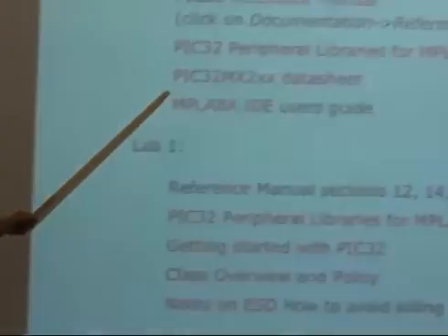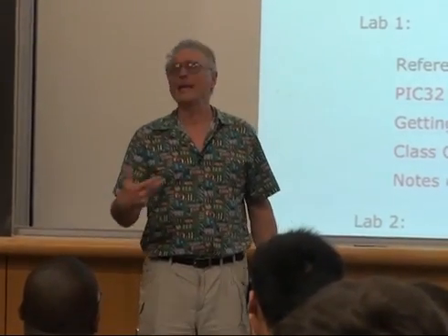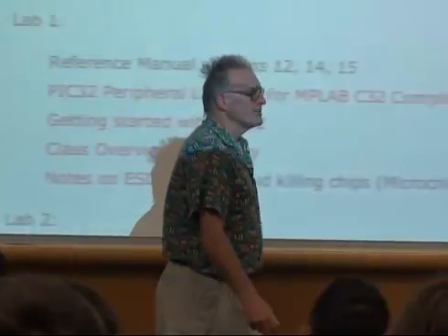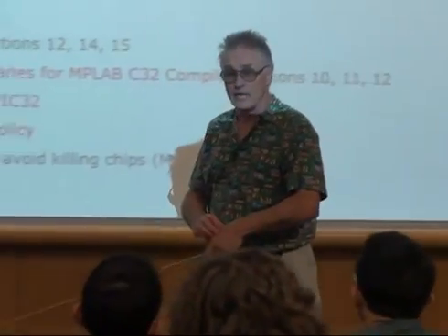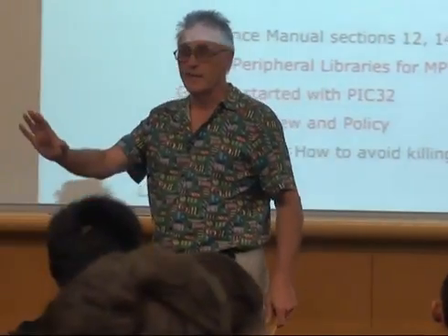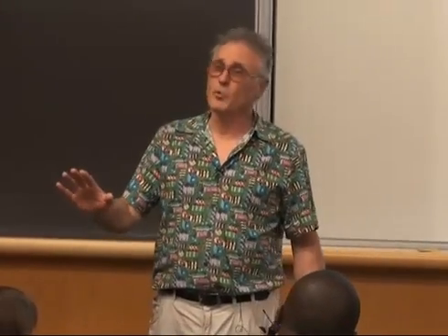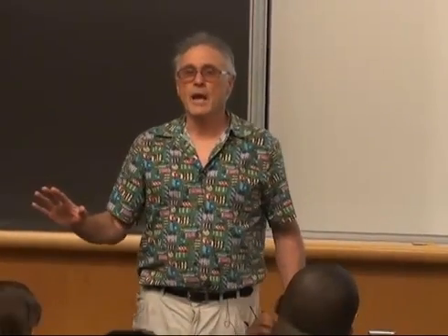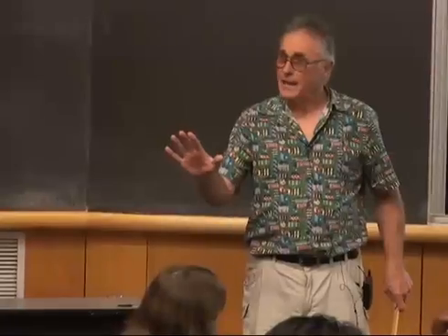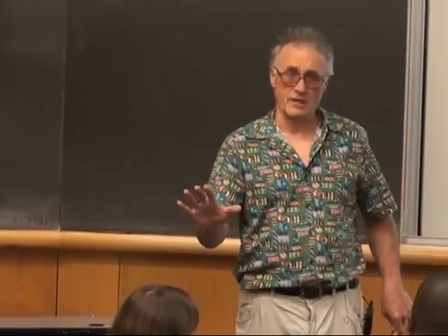The PIC32 data sheet has the gory details of the pinout, and this chip comes in several pinouts. We're going to use the 28-pin PDIP. The nice thing about using PDIP is that when you blow out the I/O ports, you could replace the CPU. Not that you will, but you probably will. And that's okay. This is a hardware course. You can't learn to build stuff unless you learn to break stuff and fix it.